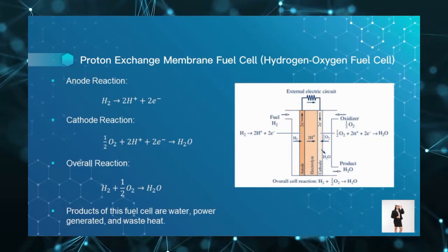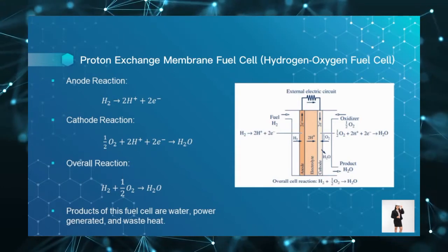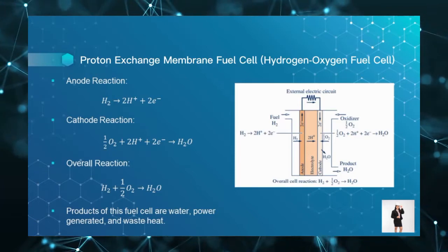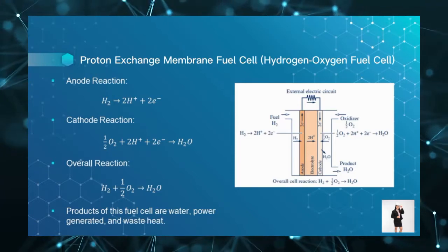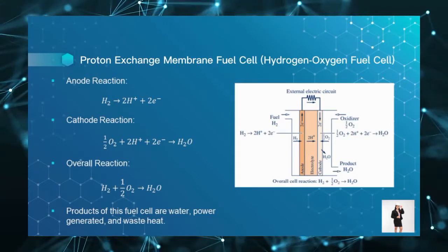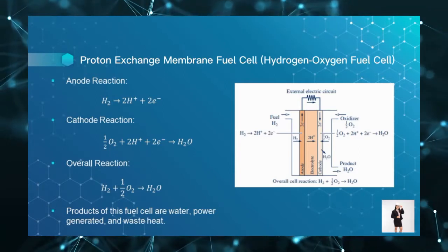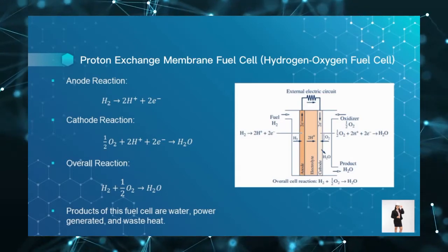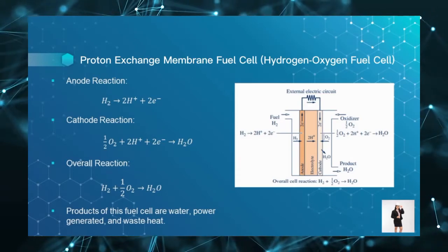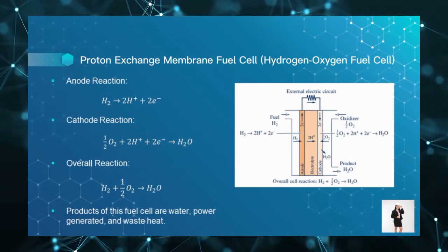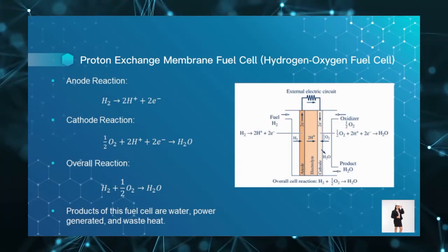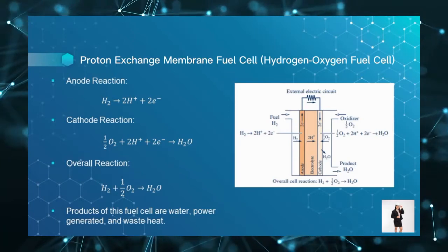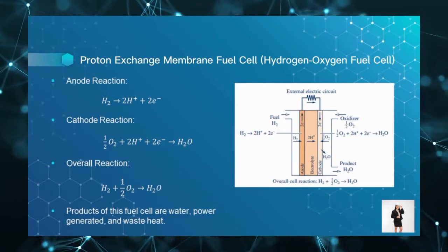When the hydrogen fuel enters the left inlet, it is oxidized by the anode, which means that each hydrogen atom loses electrons to become a hydrogen ion. Then, the electrons go through an external circuit, creating a flow of electricity. The protons at the anode migrate through the electrolyte to the cathode, where they unite with oxygen and the electrons, and this reaction produces water and heat.